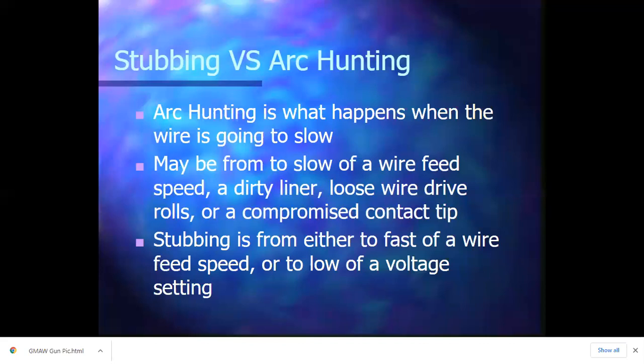So that wire is coming in and crashing into that weld puddle, and it's popping and busting off chunks of wire. It doesn't even get to melt the wire. What happens is that wire comes down, it hits, it rolls over, and then short circuits. That piece is going to pop off. That'll land in your weld, beside your weld, and you've got little chunks of wire all over your plate. It's just not very good at all.